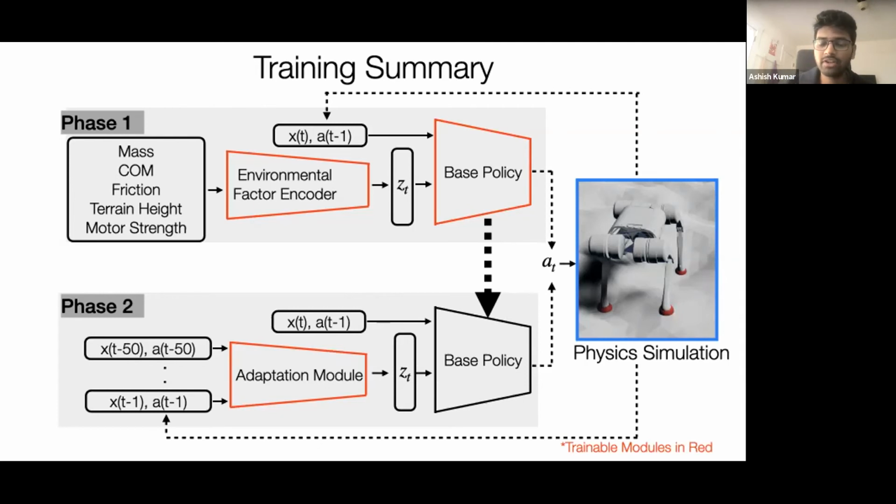But another benefit of this decoupling is the asynchronous deployment that you saw. If we trained everything at 100 Hertz, and let's say part of it was only able to run at 10 Hertz, we would see a degradation in performance. You kept everything the same, and you would just change the objective for the adaptation module. So you would keep the compression and the different Hertz thing. Yeah, but then even if I trained this, let's say I trained phase 2 directly. Right, that's your question. Yeah, that's right. Even if I did that, the adaptation module at deployment now needs to run at 100 Hertz because there is no guarantee that this is not changing at 100 Hertz.